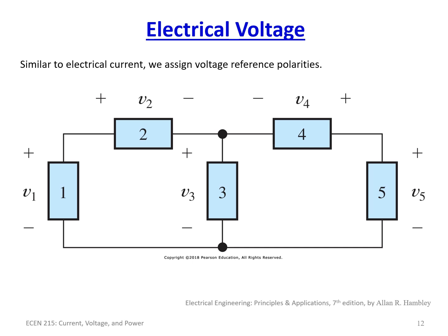So for instance, for voltage 2, we would measure it from the positive to the negative terminal. For voltage 3, positive to the negative terminal, and so on and so forth. Always, again, pay attention to what you assign, as the person doing the circuit analysis, as the voltage polarity, so that when you apply Kirchhoff's voltage law, you apply it correctly in your equations.